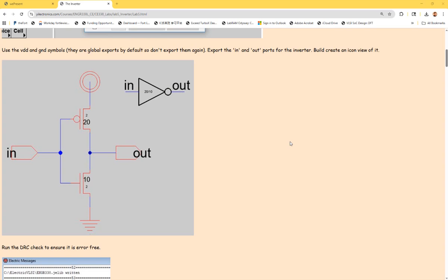Like I said, for this circuit, it's still just 1 layer. 1 layer means you just have 1 transistor level circuit and wrap it into a symbol, and we don't have another upper layer circuit. Just for example, if we need maybe 10 inverters for another layer of the circuit, one thing you need to know: you can see I don't have a connection for VDD and ground. However, you can assume that at the upper or higher level of the circuit, you wrap it with multiple layers, but eventually the VDD and ground are still exported to that layer.